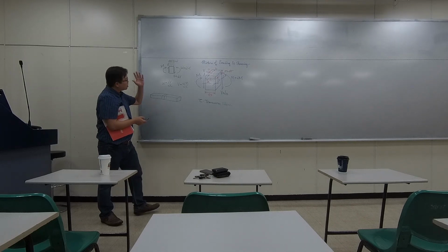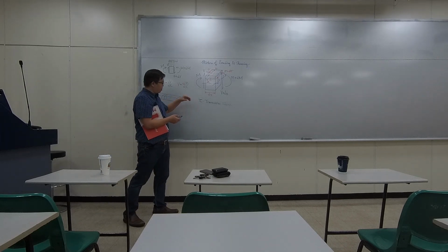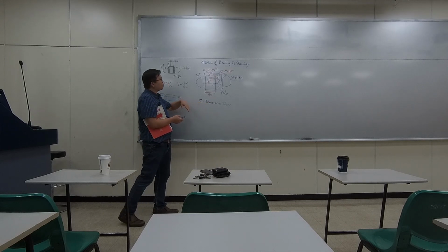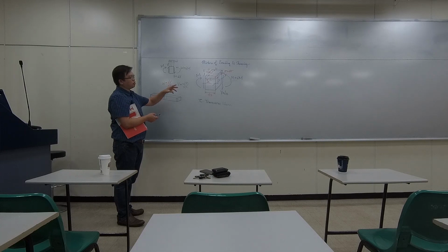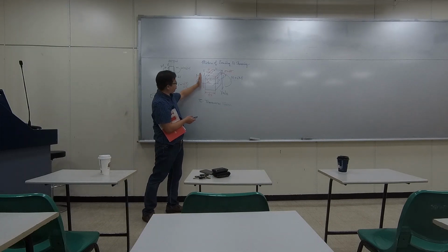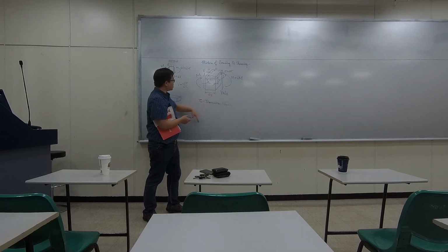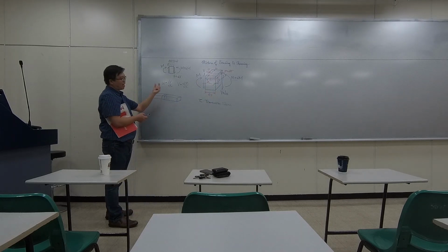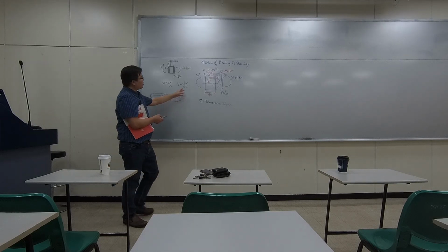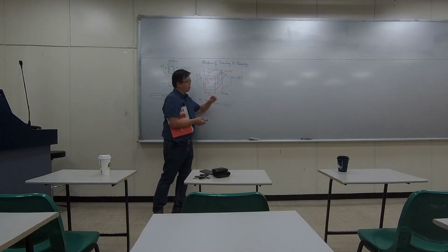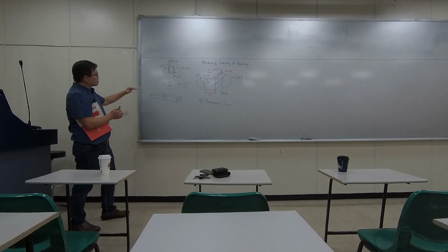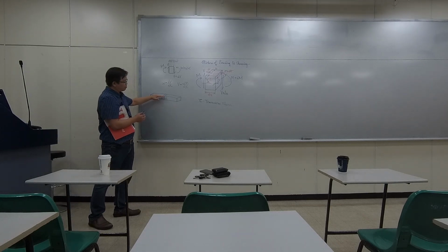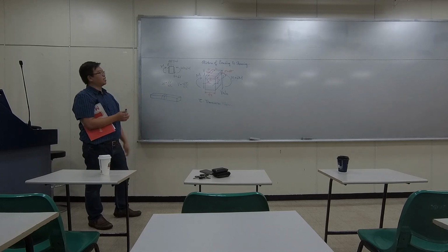And we need to deal with transverse shear when there's both bending and shearing. Meaning we have a change of shear on the left and the right hand side of that cut, and there's a change of your moment from left to right. When that happens, there could be shear at the middle, horizontally.